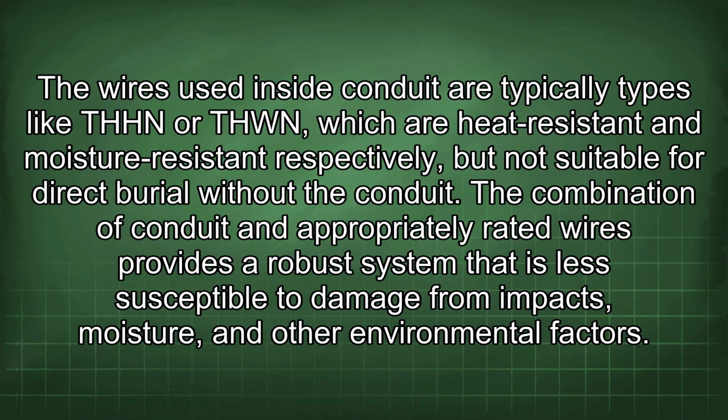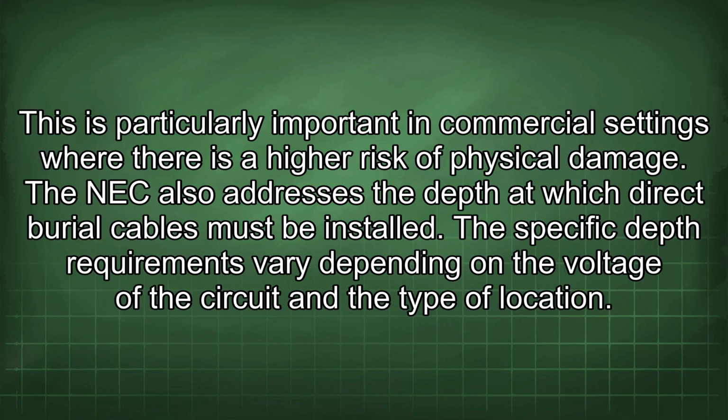The combination of conduit and appropriately rated wires provides a robust system that is less susceptible to damage from impacts, moisture, and other environmental factors. This is particularly important in commercial settings where there is a higher risk of physical damage.